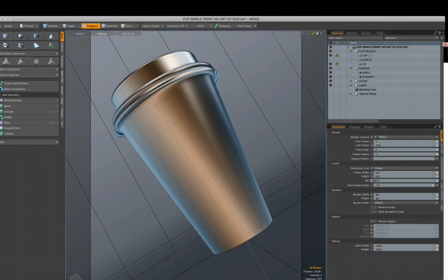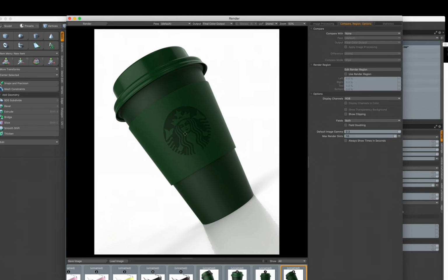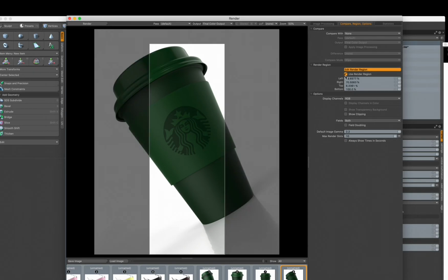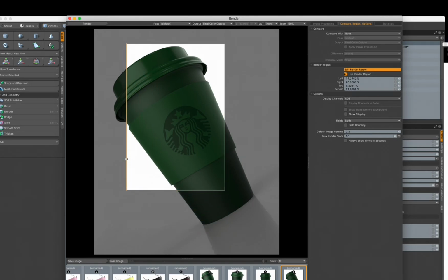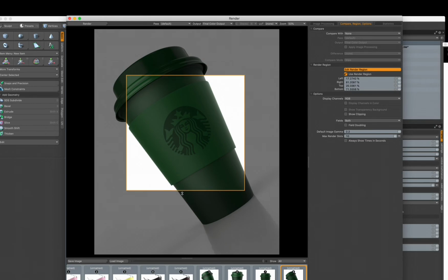So if you go here, let's go back here. Obviously on this you won't see what's in the preview because this is the image generator. But if you click here where it says edit render region, this allows you to drag these little handles, right? And drag it here, and I just want to generate this area out here, because I have all this additional information. Unfortunately, we can't just draw around it. It's just based on area. But if I want to render now, and you're going to see everything you see here, but without this, you just click render.